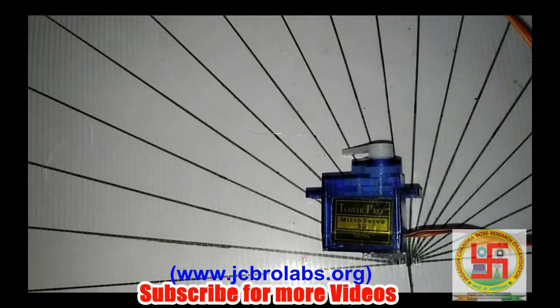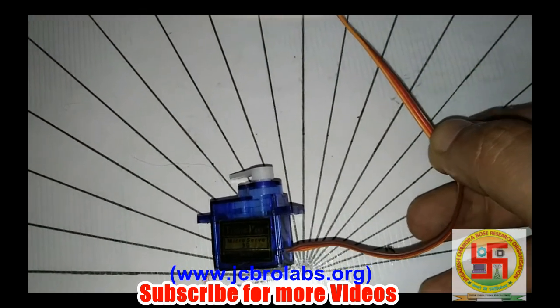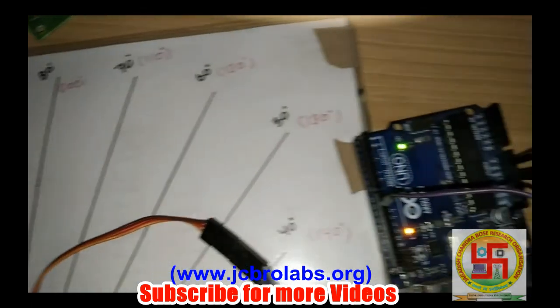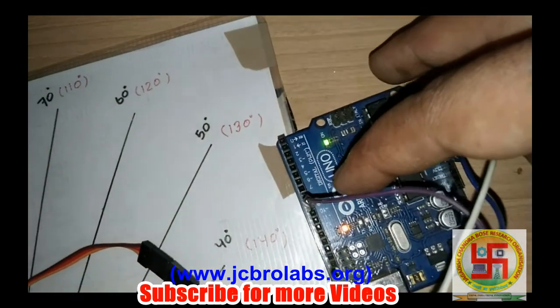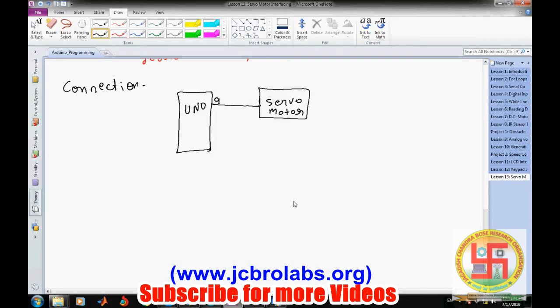The brown wire is ground, the red wire is VCC, and the light yellow wire is connected to the PWM, pin number 9 of this Arduino. So you have seen the hardware setup.